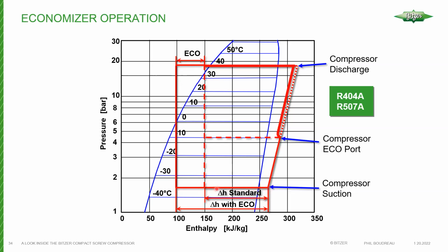So we're able to achieve more refrigerant in that evaporator for a given set of conditions. Now, in order for this to happen, on the opposite side of that heat exchanger, we have a refrigerant boiling that enters some intermediate point within the screw compression process where we compress the refrigerant. And that has to take place after the refrigerant is drawn into the suction end of the compressor, and then those rotors trap the refrigerant.